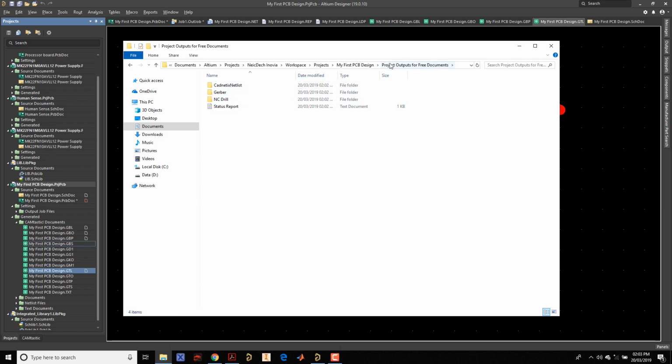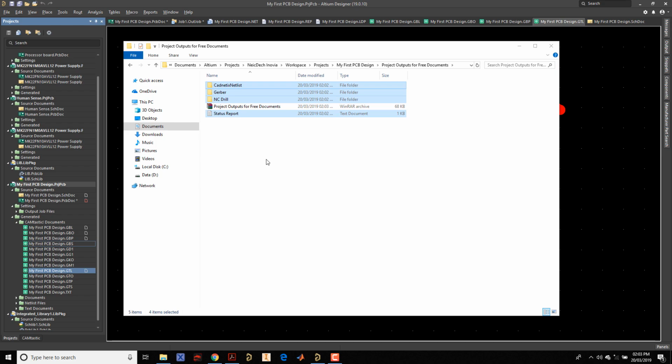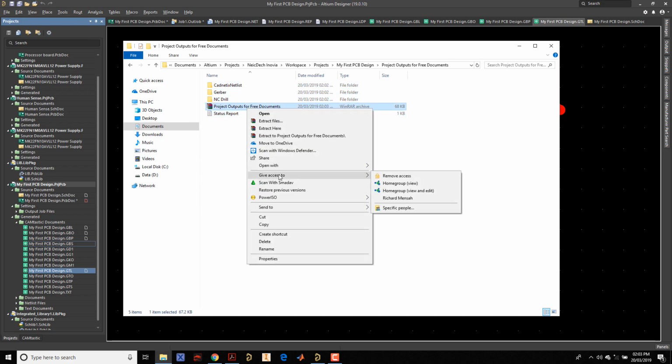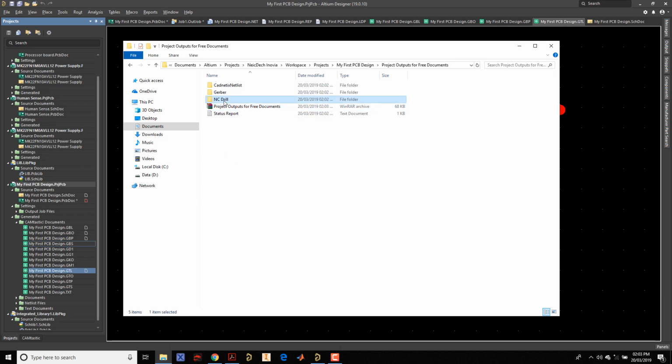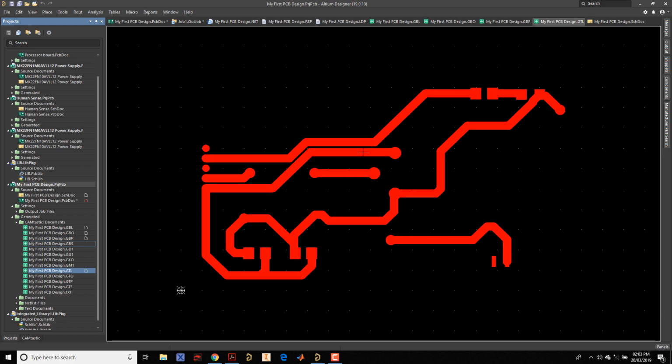All that we have to do is just do this. Add to document. Rename it, upload it online, and that's all. In maybe about 7 days, you have your circuits back. So you send them the drawings, the Gerber files, and this, and then you bundle them together as a raw file, and you compress, and then you send it to them.